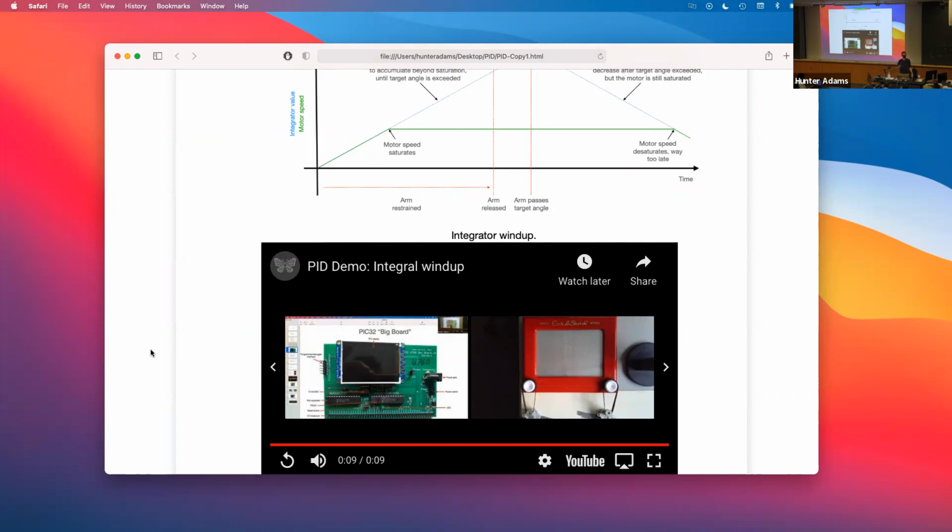And the way that I recommend implementing this integral term is, rather than sum all of the error since the system booted up, instead consider summing all of the error for as long as the sign of the error hasn't changed. So if you're down here and the sign is large and positive, you sum up until it's negative, and then you start a new summation. Okay. But when you start that new summation, don't zero the integral term.